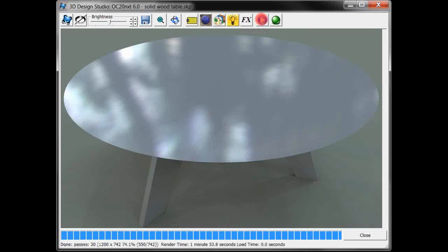So that's one option. Another nice option that we have, and I think particularly helpful, especially when you just want to check the integrity of your geometry, is to use a clay model rendering. So here's exactly the same model, materials suppressed and overwritten by our model in shades of white, as though it were made out of white clay. Also a pretty nice rendering of the model.